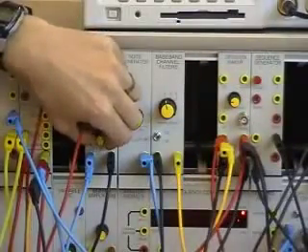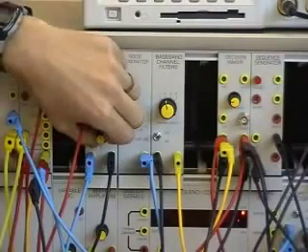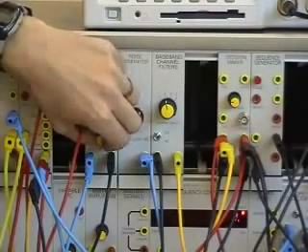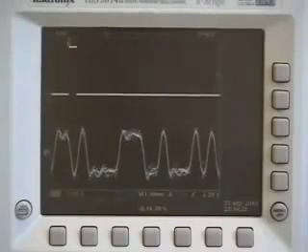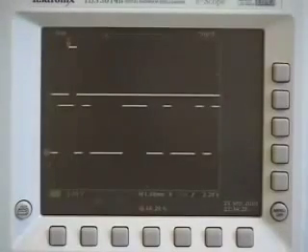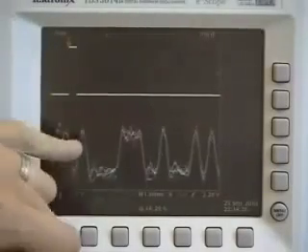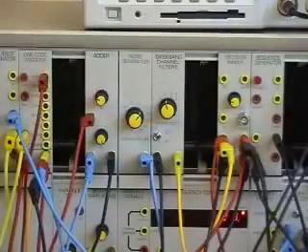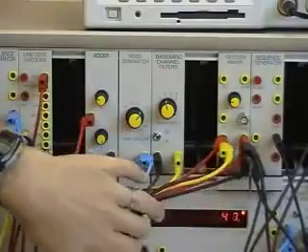After alignment, increasing noise in the channel creates errors, which we can measure to define bit error rates, and use a true RMS module to measure signal-to-noise ratios of the channel. We can then plot bit error rate versus signal-to-noise ratio for this signaling scheme and compare with theory.